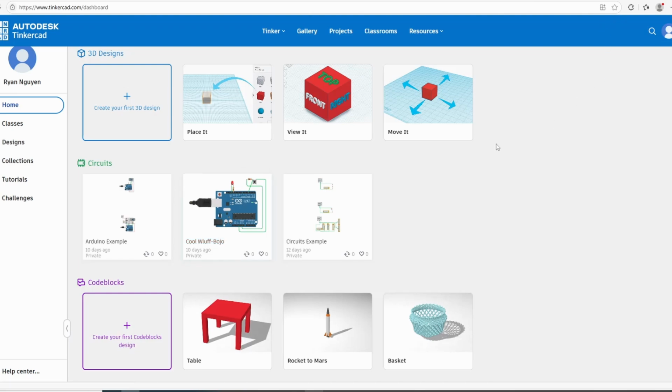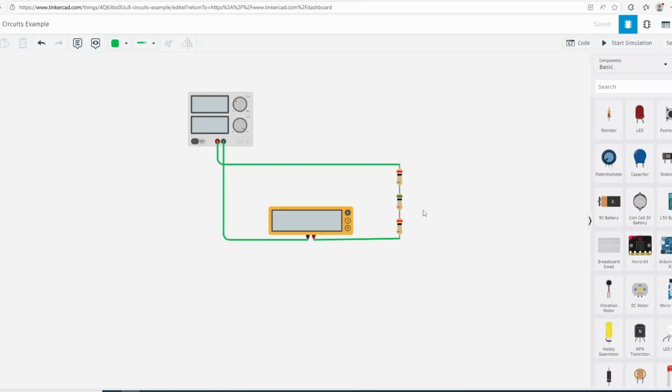I highly recommend experimenting with different things here. It's free, and it'll help you learn the basics. Alright, so here we have a circuit, and in Tinkercad you can go to the Circuits tab and essentially drag in objects, and then connect them, and then you can use wires to connect more stuff together. So that's basically how I created the circuit.